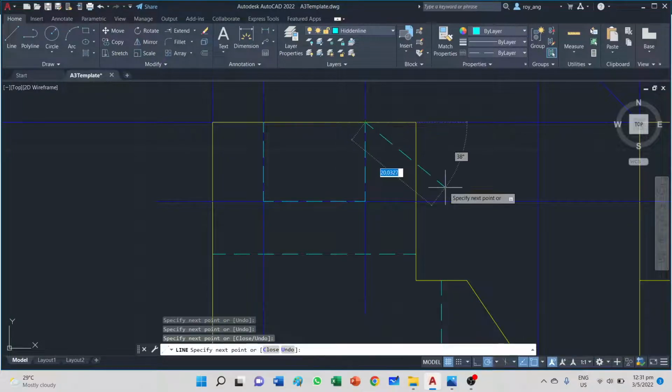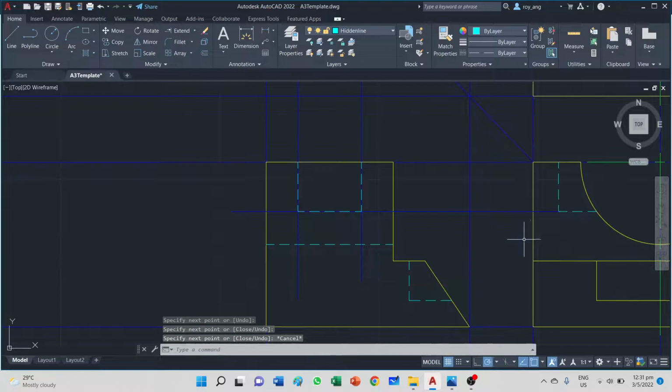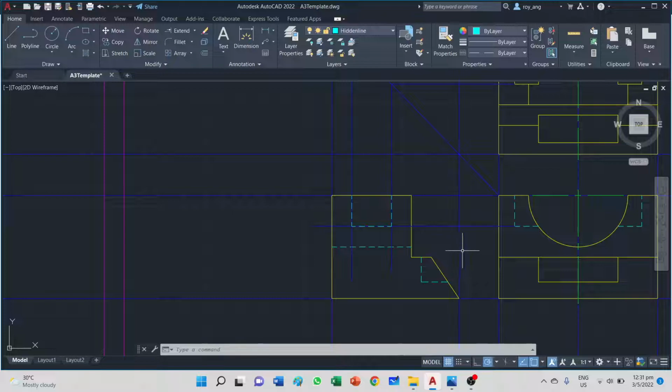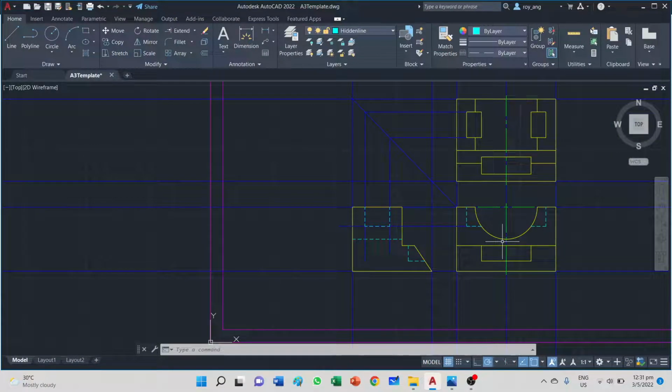So you don't have to worry that you click on the wrong projection. Projection works very well if the drawing is rather simple and that is the only intersection there, but it can get quite dicey or really difficult if there are many points in the vicinity and you could accidentally project from the wrong point, and that would be a very bad mistake. So if let's say it's a very clear-cut drawing, you can use the projection, but if it gets really messy with a lot of corners and points there, you can use this technique of using the construction lines to draw across. Okay.